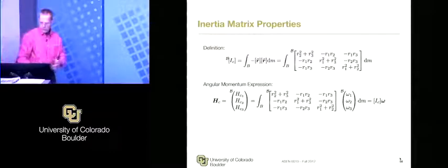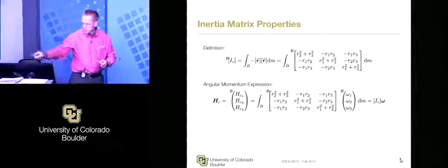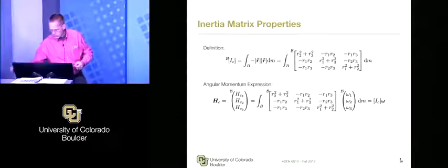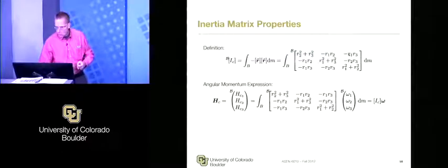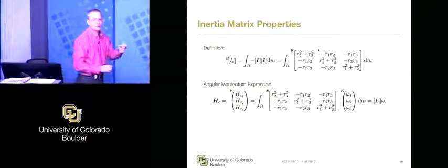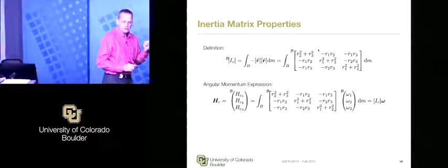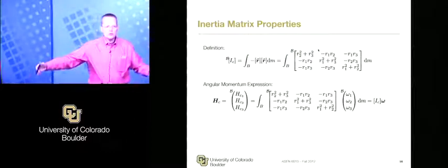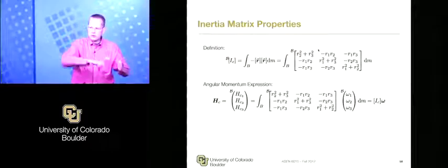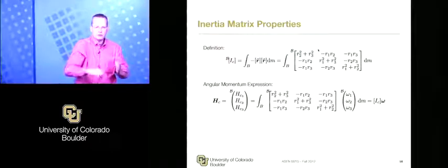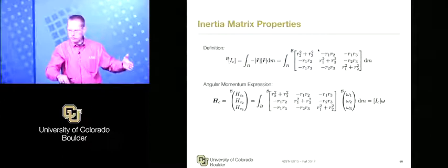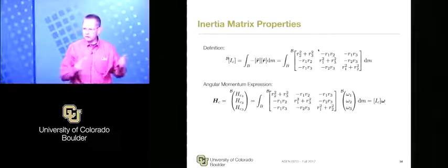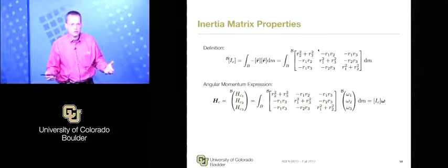Now, looking ahead, again, this is more supposed to be a review. Here we're choosing to take vector components with respect to this body frame B, and all the vectors are taken relative to the center of mass. What if we don't want to take the moments about the center of mass? Maybe you have a solar panel, and what you need is the inertia about the hinge axis at the end of the panel, but the book tells you the inertias about the center of the panel. How do we go from this to the other one? Do we have to redo the body integral?